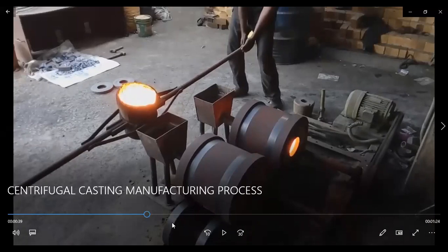You see, with the help of a mechanical attachment here, these barrels are able to rotate. They are made to rotate, and when the molten metal is poured in, it distributes throughout the circumference because of the centrifugal force, because they are rotating at high speeds. That is what helps the material to accumulate on the periphery. Very simple. Just as you have in the washing machine, the clothes try to get away from the center. Same thing here. The orientation is not as you have in the washing machine; it's 90 degrees to that. So you observe that this is the molten metal being poured, and with the help of these channels, it will go inside this setup.